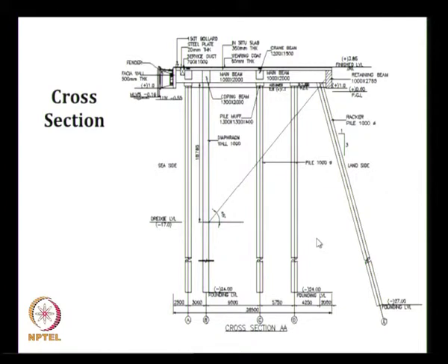Especially civil engineers will know that in a truss system we have some redundant members. There we had only one main sheet pile wall and an anchored wall with a tie back system, whereas here we have a diaphragm wall made of concrete, then two vertical piles and one raker pile.